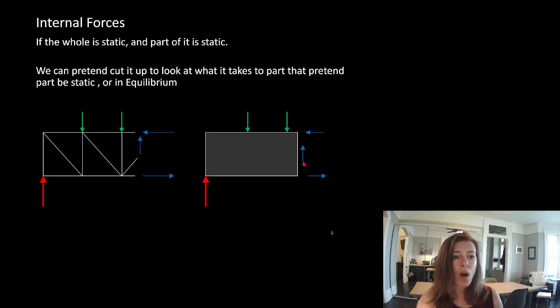Okay, so I've got the Y component of my web element, and I've got my top chord force, and then I've got the X component of my web element and my bottom chord. Well, what if I redrew these as an internal moment? Okay, so it seems like now, instead of drawing some unknown placeholders for the internal axial forces,